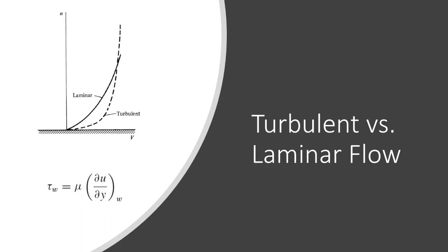In turbulent flow, due to the agitated motion of the fluid elements, the higher energy fluid elements from the outer region of the flow are pumped close to the surface. This results in a higher average flow velocity near the surface of the object and a different velocity gradient than in the case of laminar boundary layer. We can thus conclude that the velocity gradient for turbulent flow near the surface is higher than that for laminar flow, and hence skin friction drag is higher. However, since the fluid elements' average velocity is higher in turbulent flow, the fluid elements have more energy to push against the shear stress and the adverse pressure gradient. This delays flow separation, or in some cases prevents it, and hence reduces or eliminates pressure drag.